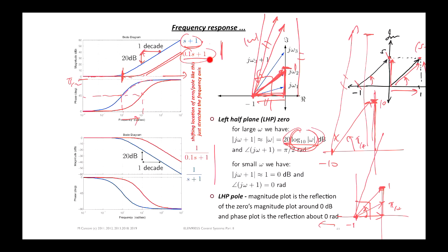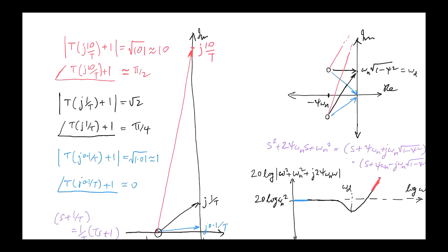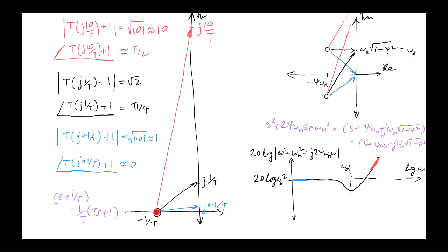The point of looking at these terms is that at low frequency they always have a gain of 1, because when I evaluate this at s equals j0, I'm just left with 1. Right? So that's why we normalise. But to draw these vectors, you can't normalise first. Okay? Effectively what we're doing is moving the origin to what makes this function evaluate to 0. Okay, so to figure out what something like this would look like, we would have to look at these little vectors and multiply by t. Okay, which will change the magnitude but won't have any impact on the phase.